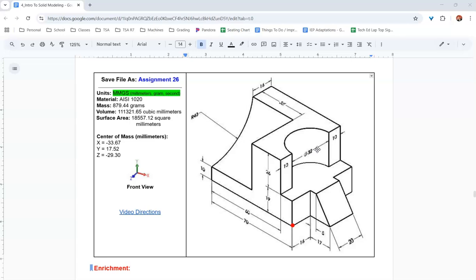I'm looking at this like, if this cutout wasn't here, if this big piece wasn't cut away, this whole entire back piece would be one big solid piece minus this little curve. So I could draw that all as one chunk, and have that little curve in that same sketch. This same thing is just one big piece as well. So I'm not looking at it from the front view or the side view. I'd be drawing this from the top view, and then I'd do something different to cut this on an angle and remove that away. So just by looking at this, I know I'm going to be drawing from the top view.